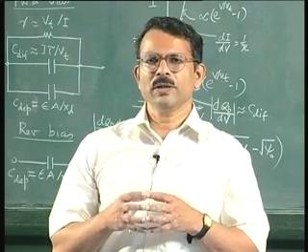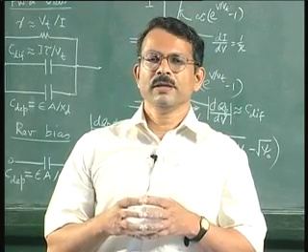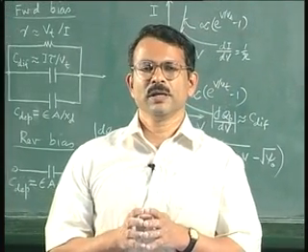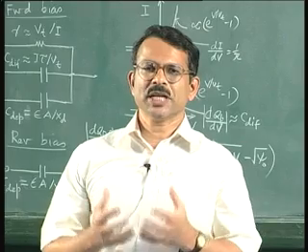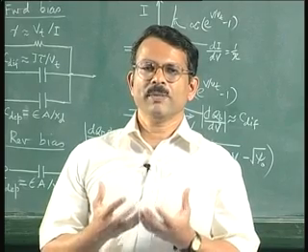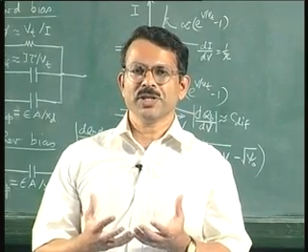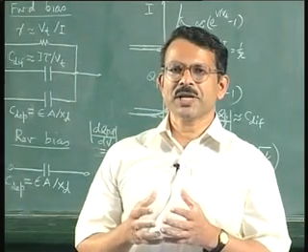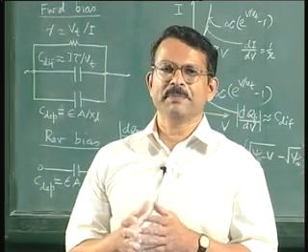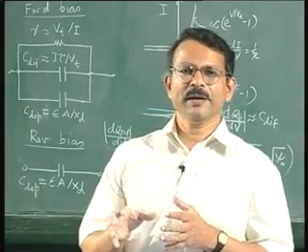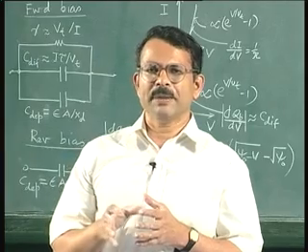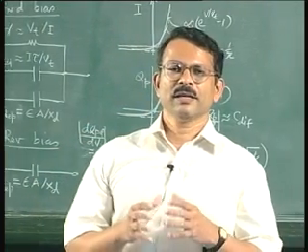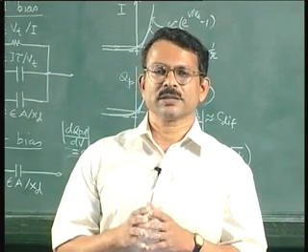Now as we have pointed out, in silicon diode the generation current dominates on the reverse side as compared to the diffusion current. So though the diffusion current saturates, the generation current within the depletion layer that dominates the diffusion current goes on increasing with voltage. Now this generation current within the depletion layer is of the order of 10 power minus 9 amperes, okay. So that is why you are getting the reverse current of the order of 10 power minus 9 amperes instead of the 10 power minus 13 ampere current that we had used for calculating the forward characteristics, okay.